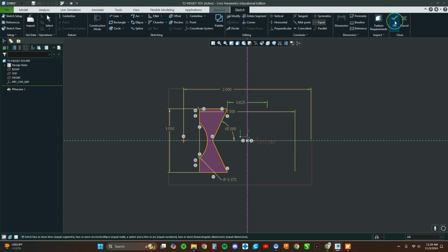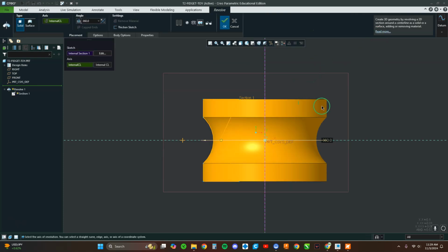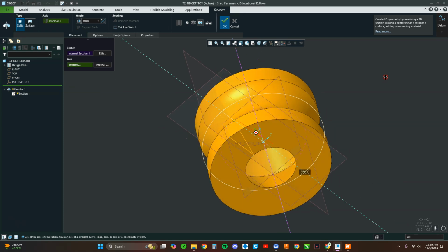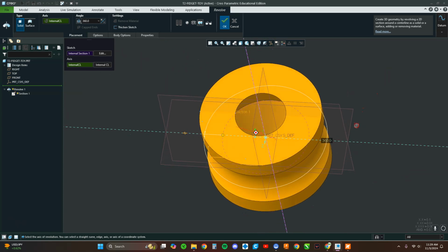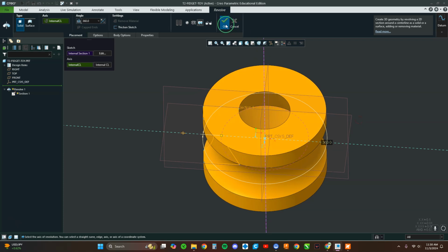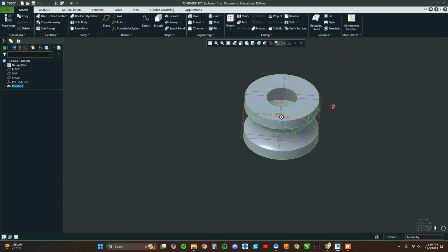is for defined dimensions, we can go up and hit the checkbox, which then we can hold down middle click, don't just click it, hold it down and rotate, and you'll be able to see your piece in 3D. Okay? The reason I said not to click it is clicking it will actually automatically hit whatever's bolded. So you can see like this is bolded in blue or highlighted in blue. If I middle click right now, it's the same as clicking this. So you can either click your checkbox or you can middle click and it'll create your piece. All right, so there's our piece.